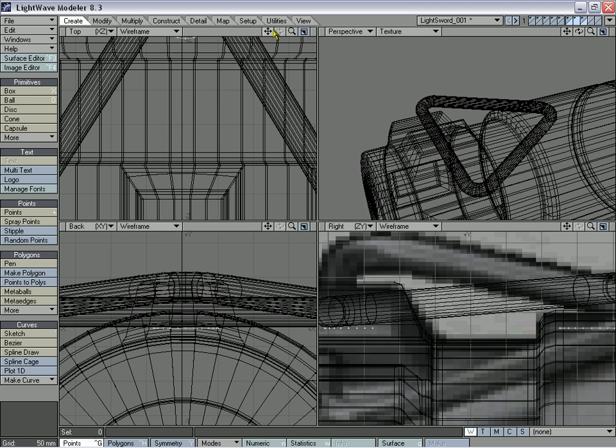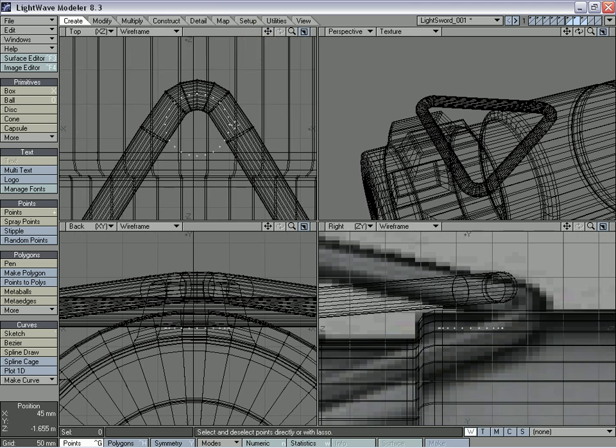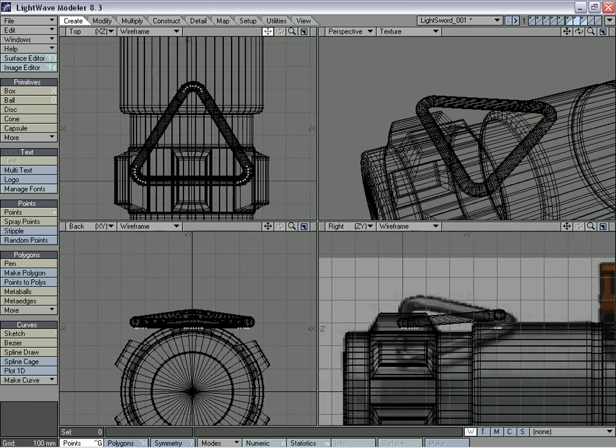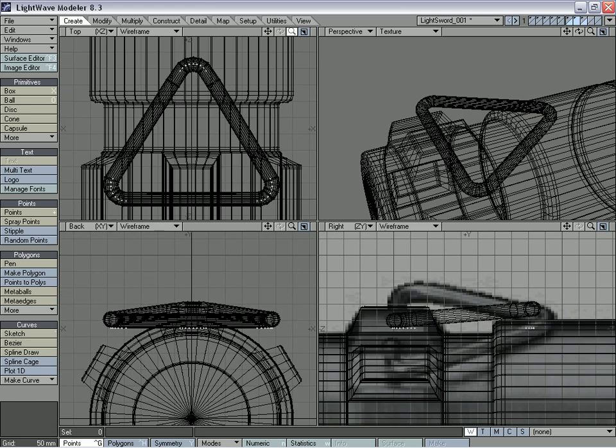Okay. And hit K on the keyboard to kill that polygon. And now we can delete these points that we don't need. And now what we're going to do is pretty much the same thing as creating a polygon. We created a spline earlier too, but this is going to be a closed spline. So we're going to select these in order. Now before we hit Control P to create our spline, as you notice there's a large gap in here. So we're going to undo that, and if you hit Control O, it'll create a closed spline.